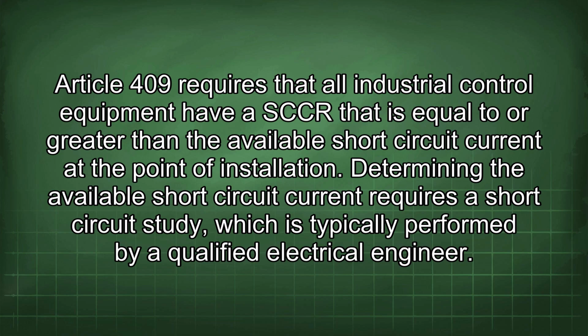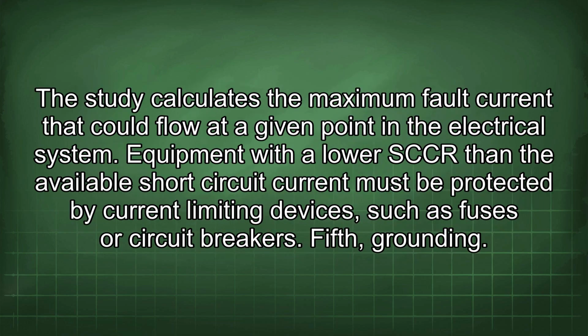Determining the available short-circuit current requires a short-circuit study, which is typically performed by a qualified electrical engineer. The study calculates the maximum fault current that could flow at a given point in the electrical system. Equipment with a lower SCCR than the available short-circuit current must be protected by current-limiting devices such as fuses or circuit breakers.